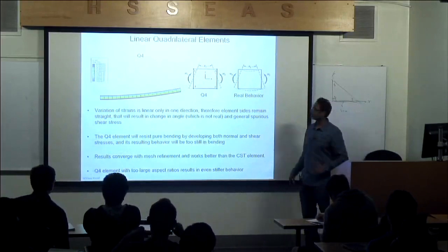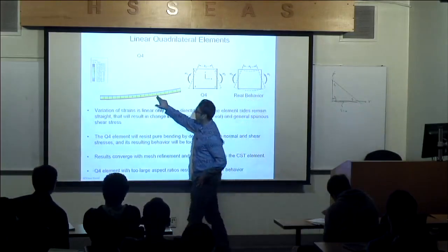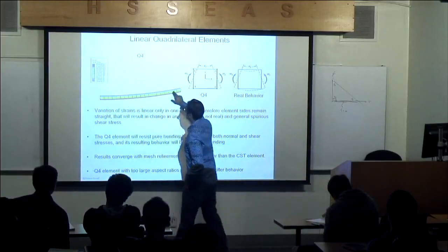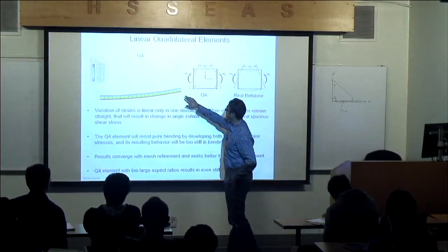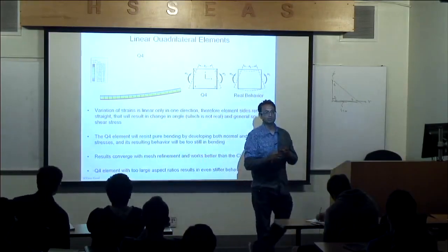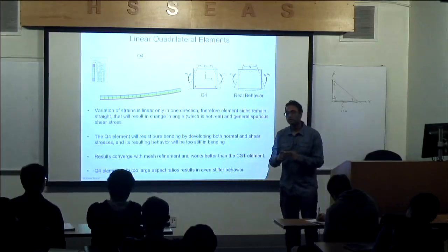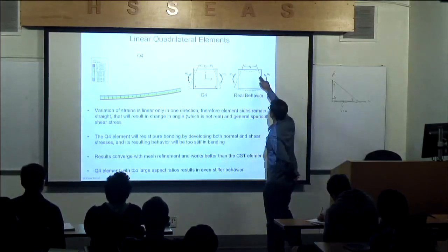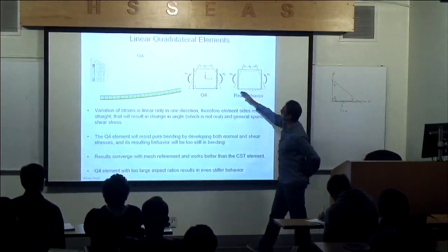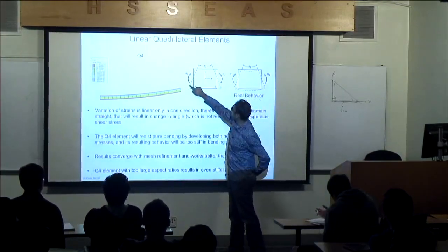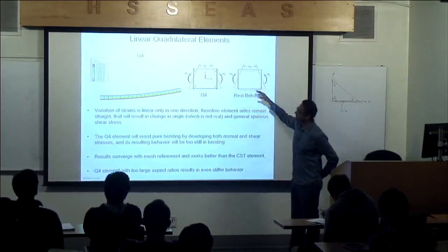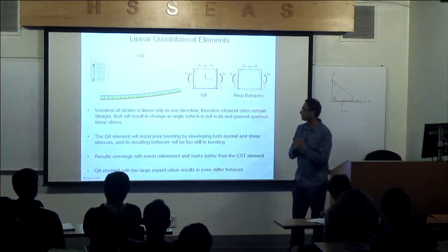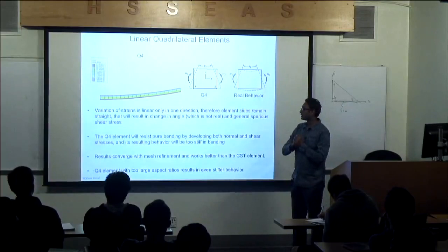The linear quadrilateral element, a single element across, Q4, will behave a little bit stiff also. The reason for that is that the bilinear displacement field we have chosen does not allow you to represent curvature very well. It only allows you to basically model this kind of situation, and does not allow you to model this situation. For that reason, you're also going to have an overly stiff behavior, and some amount of shear locking in this type of element.